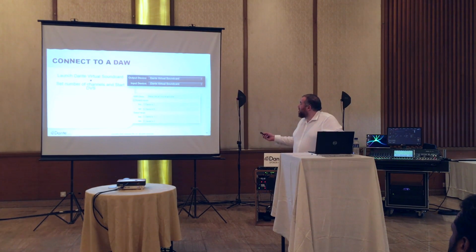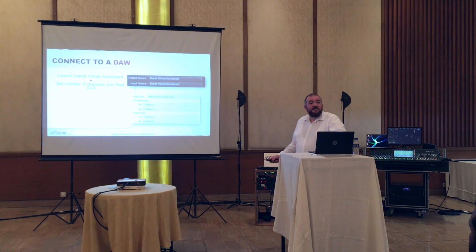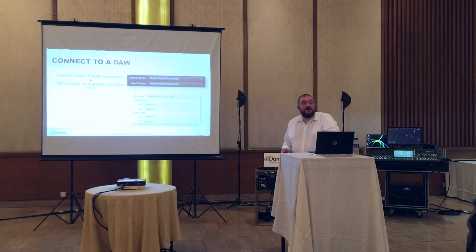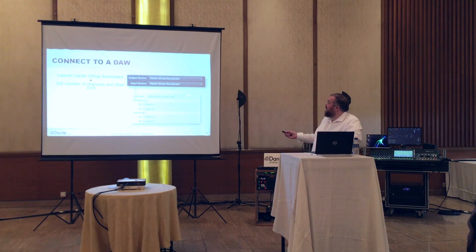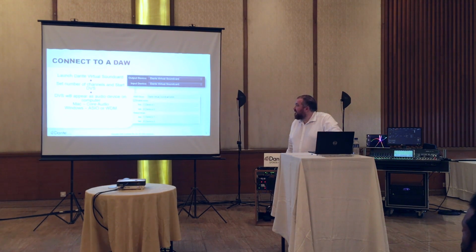So connecting to a digital audio workstation, this looks vaguely like some kind of Apple Logic type thing. Dante Virtual Soundcard will show up just as a normal sound card. In Apple, we use it as a Core Audio device, so that will work across a whole plethora of things. In Windows, we support ASIO and also WDM. The WDM driver will only do 16 in and 16 out. ASIO will do up to 64 in, 64 out. And again, it shows up as a virtual sound card, just a normal sound card, and then we can deal with which channels right up to our 64 in, 64 out, if we so wish.